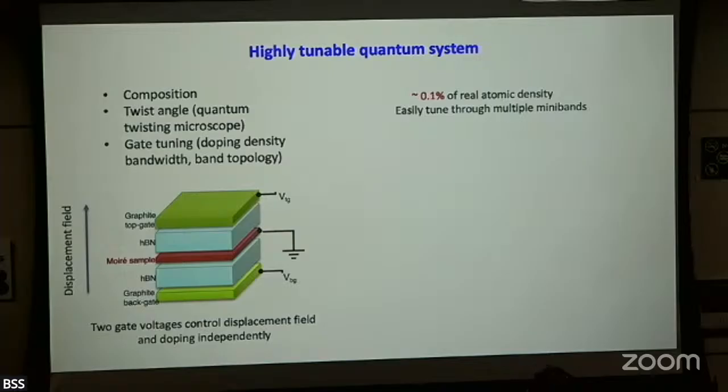And so with those two gates, the other thing you change is the displacement field. I gave an example yesterday for this optically detected resistance and capacitance. In that case, the property is not very dependent on the displacement field. But in the other example I showed, when the two layers are the same, homobilayer, you change the potential difference between the two layers, physics can change very significantly.